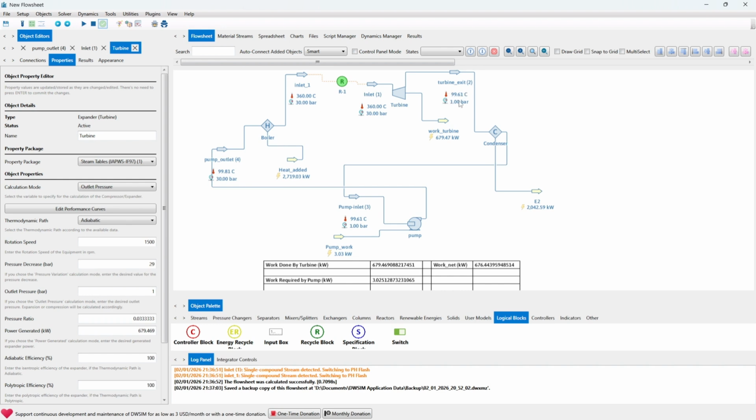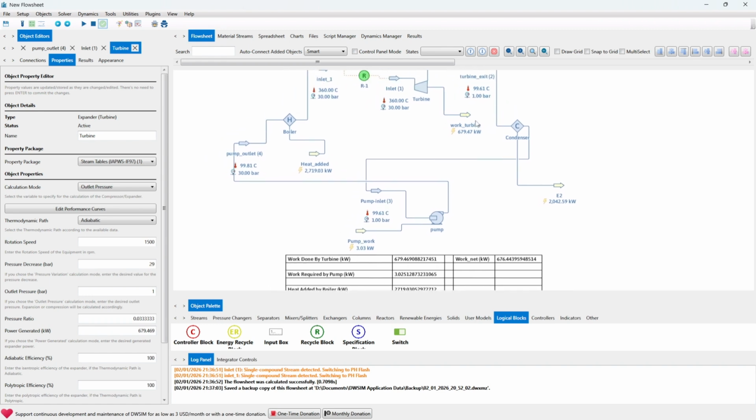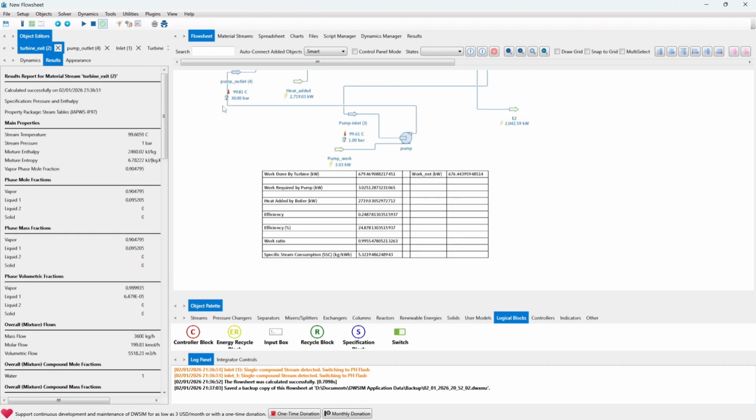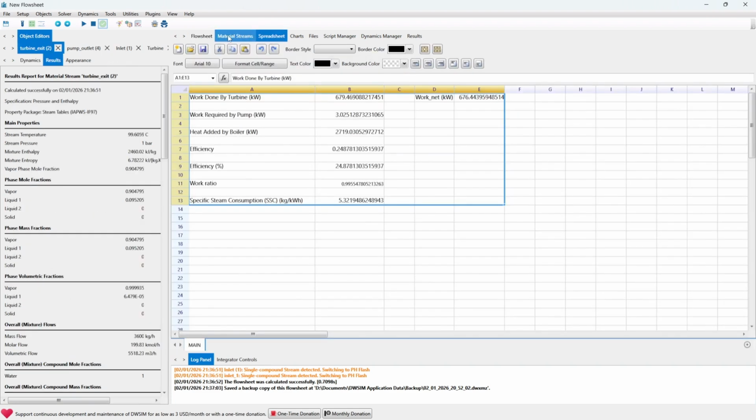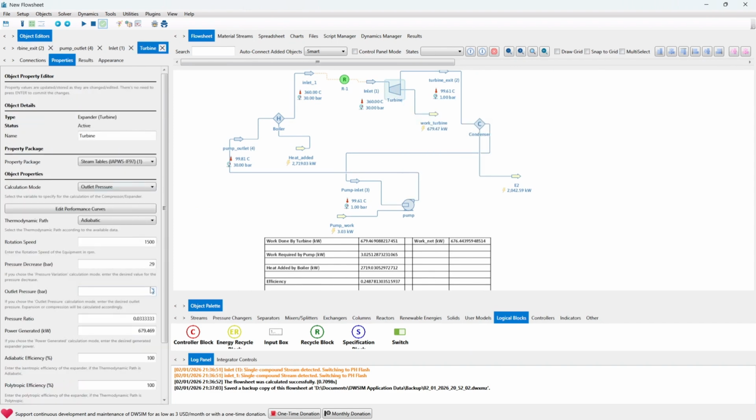As you can see, I'm using 1 bar, but the pressure at sea level is 1.01315 bars, so that's why the temperature is slightly smaller than 100 degrees. Let us just return it to where it was, the pressure to be 5 bars, so that it can be the same as that for Carnot.